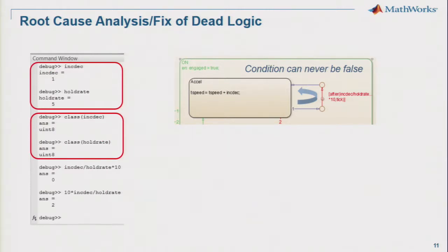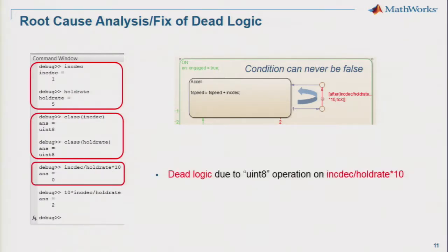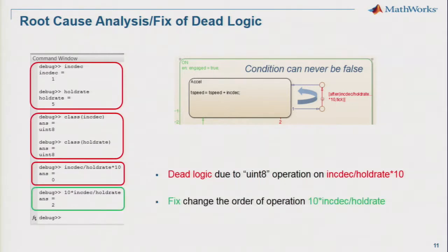So rather than have this maybe be uncovered in functional testing, we're showing this early on by using Design Error Detection to define this early. And then we can play around with the order of operations, and we can see, yes, in fact, that's always 0, so that after condition would always be true. But if we rearrange it, we find out that we can fix it by just changing the order. So again, that can save us some time for the functional testing.